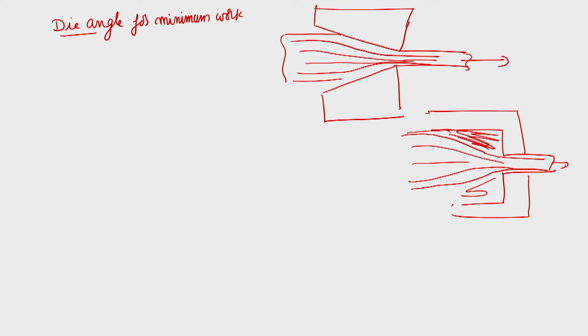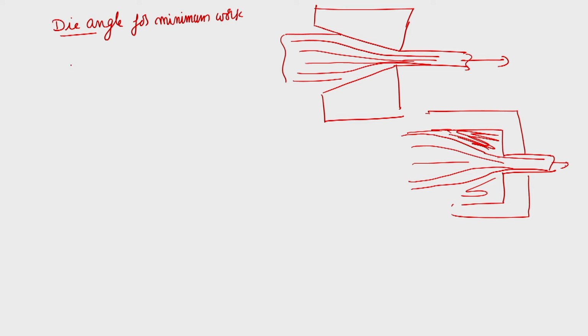So when you look at it, you have to have a minimum die angle, and several empirical and derived relationships were proposed. One by Westrich was that the minimum die angle alpha star is equal to, and in this lecture I am not going into the derivation of all these things, so that these details can be used by practicing engineers, mu into your reduction by 1 minus r, where r is the reduction in cross-sectional area.